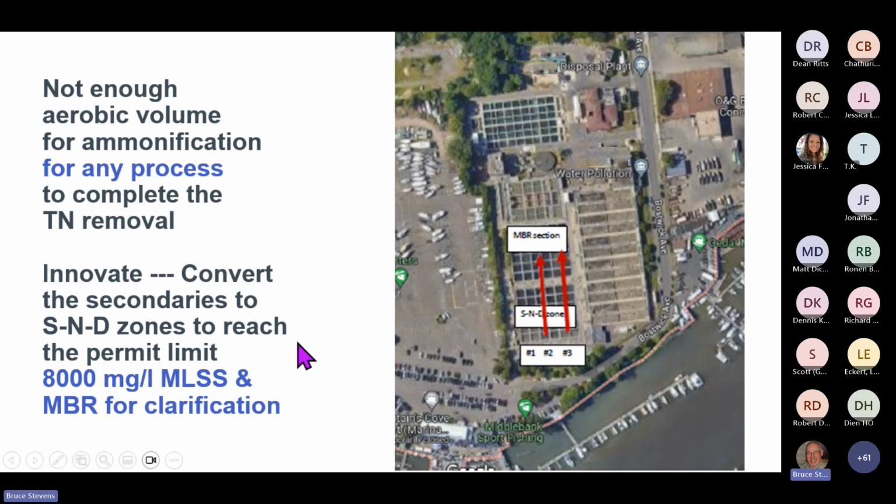So we looked at it, and we can see in the secondary clarifier trains, there are 3 trains that run back this way towards the effluent chlorine contact tanks up here after the primary aeration basins feed down a flume and across all 3 tanks. So it's our thought, these are 11, 12 feet deep, so we can put MABR towers in this first half of the secondary clarifiers. And constructability wise, I think we can do them one at a time and retrofit these.